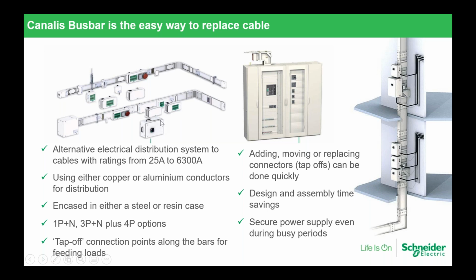For instance, if your load changes and you need more current to be supplied, it's easy, you don't need to shut down the bus bar entirely. You can safely replace that single tap-off with a higher-rated one or one with different protective devices inside, and you have design and assembly time savings and secure power supply even during busy periods.